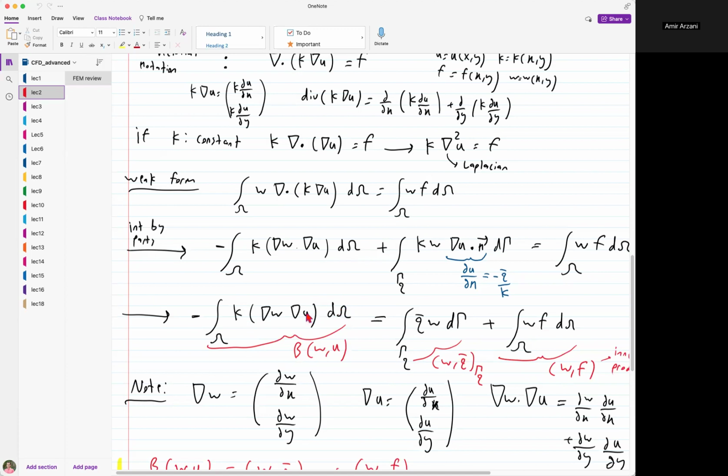So to do that, we need to assume u to be of a certain form. In finite element, typically we either assume u to be linear or quadratic functions. Now, if I assume u to be a linear or quadratic function and then evaluate these integral equations in my weak form, the issue is that if I take my domain omega to be the entire domain of interest where I'm solving my PDE, it's very likely that a linear or quadratic function is not sufficient to capture the complex solutions that we're typically after.